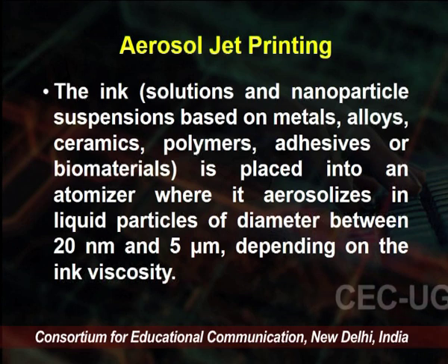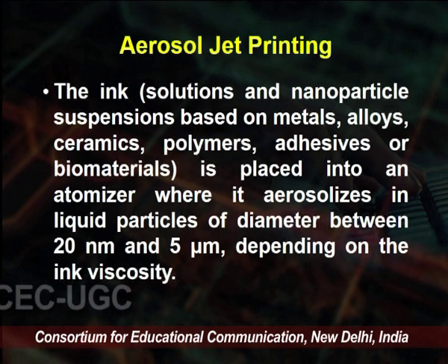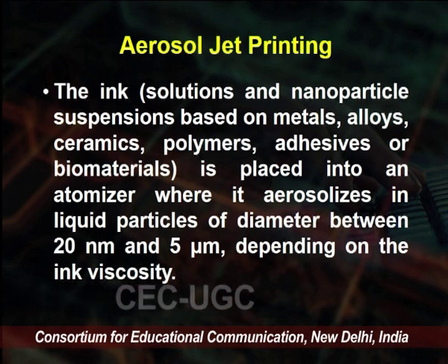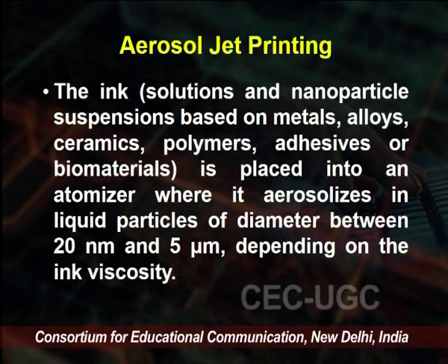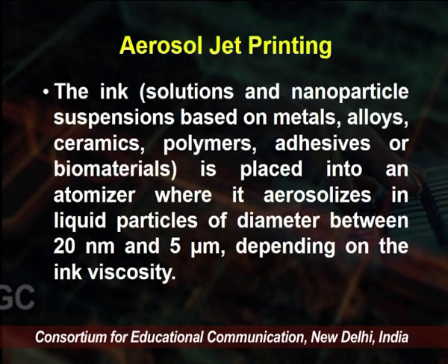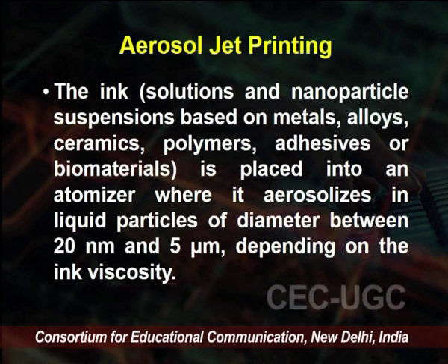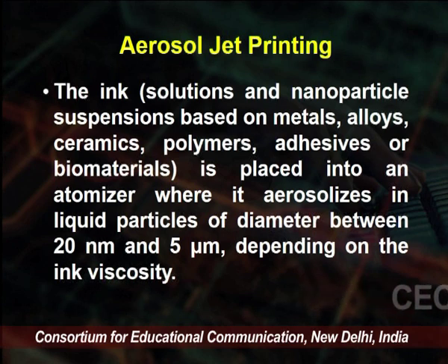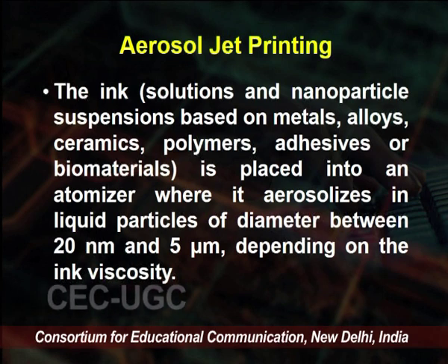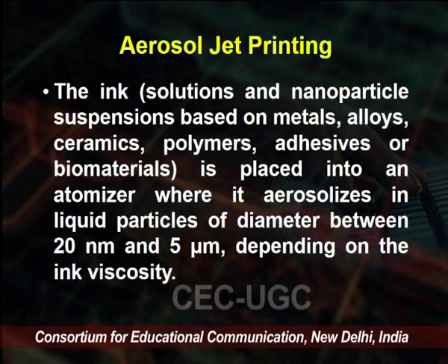The ink, which is a solution or a nanoparticle suspension based on metals, alloys, ceramics, polymers, adhesives or biomaterials, is placed into an atomizer, where we have aerosols of liquid particles with diameters between 20 nanometers and 5 micrometers.